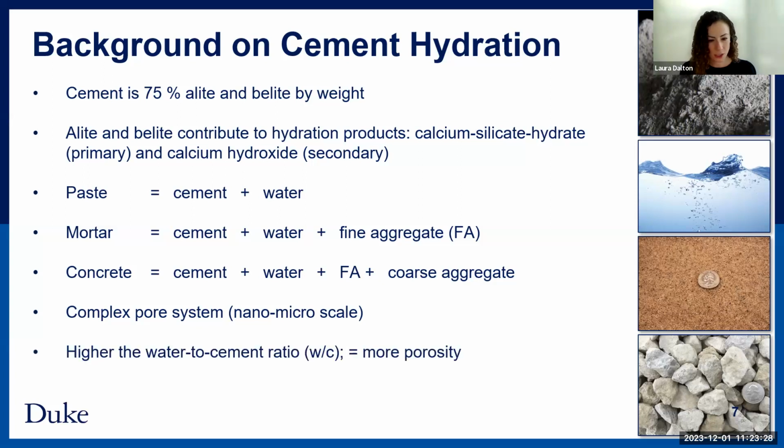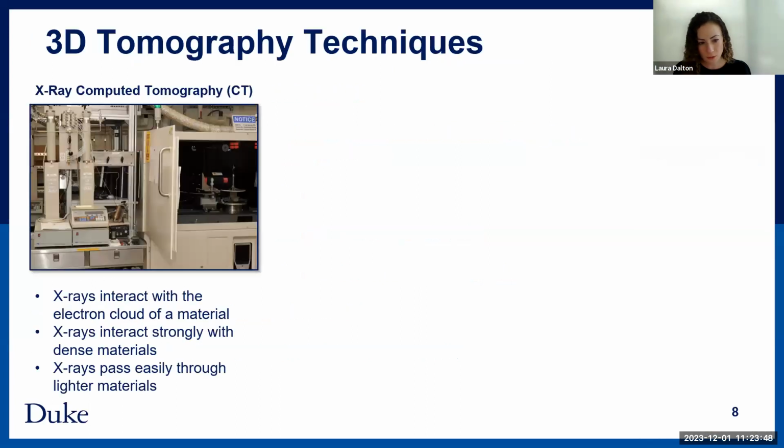And then just to mention, water to cement ratio is an important topic. It's basically the weight of your water over your cement. If you have a higher water to cement ratio, you inherently have more porosity than a lower water to cement ratio. So I just wanted to touch on that briefly.